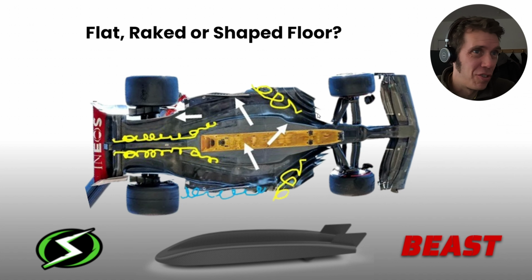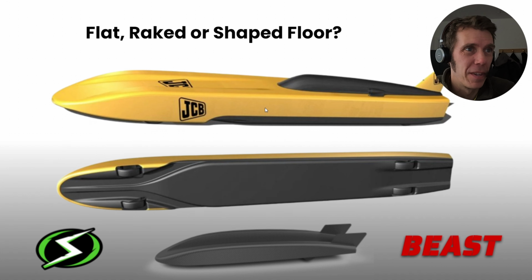So yeah, this is just another image showing the underside of a Formula One car. These sort of turning vanes try and take some of the air to the outside, but then some of it's going to go through this diffuser throat. The idea is to give low pressure underneath the car, which sucks it down onto the track.